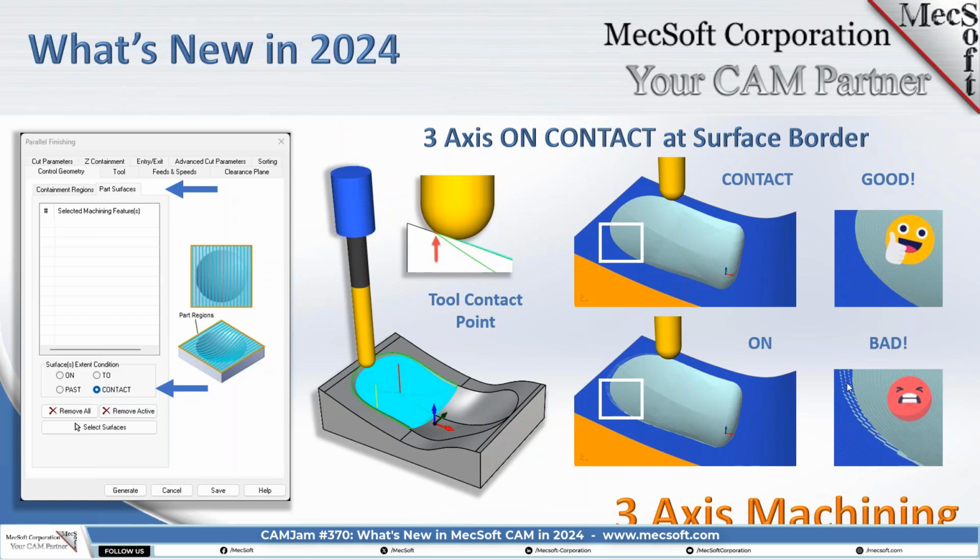And that will show up in your mold. If you're doing a prototype mold, you'll see flash. This is a flash area right here. That's not good. So in the top picture right here, without having to do anything, you just set it to contact condition. The tool stops whenever it contacts that parting line curve, and you can see in the simulation how clean that parting line becomes. That's a very good advanced enhancement that we've added for tool and die makers or mold makers.